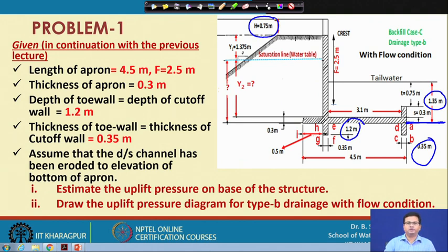You know that the uplift pressure is due to the soil pore pressure. That means there is standing water, and because of the standing water or submerged weight, the pore pressure generally develops and exerts pressure upward at the foundation material. For solving the uplift pressure, as we have already discussed, we have to use the Lane's creep theory. The weighted creep length has to be estimated.